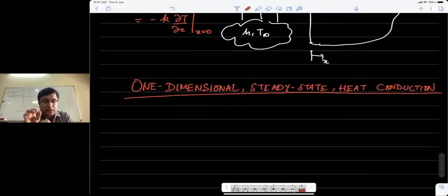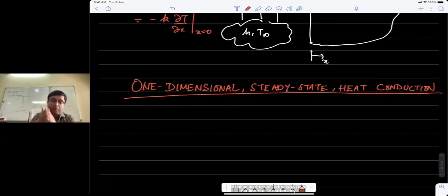What I'm trying to tell you in this case is that when you have this three-dimensional structure, three-dimensional effects are only there as long as you have not exhausted all possible variations in other directions. When you start the heat transfer, maybe the whole body is at the same temperature, and suddenly you switch on a different temperature on one end. So heat will conduct. This information will be taken in by molecules that come in contact with the hotter surface, but they will go in all possible directions. They won't necessarily go only along one direction.